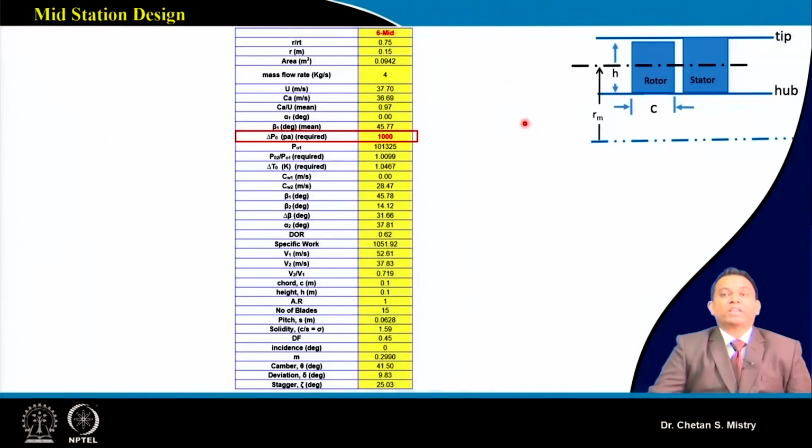Now when we are designing our low speed axial flow compressor, we do all our initial calculation at the mid station. Here, this is my mid station, and that calculation, the axial speed, remains the same for the free vortex, fundamental method, as well as for the forced vortex method. So my mean line calculation will remain the same as we have done for the past 2 methods.